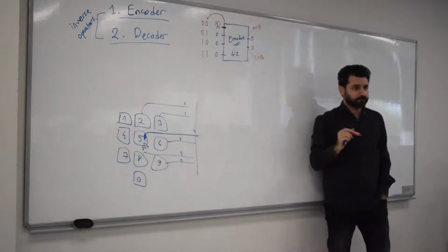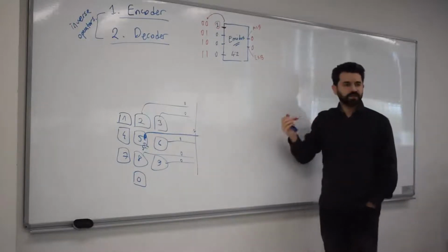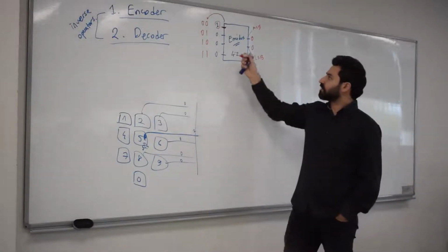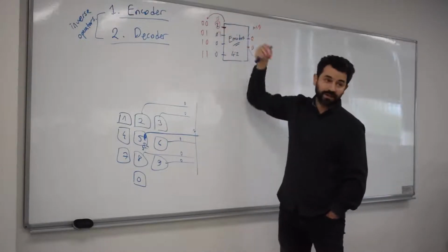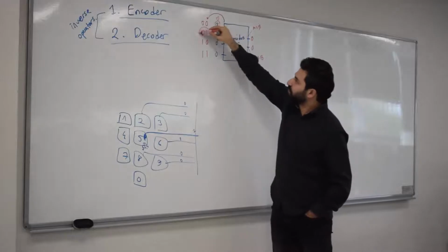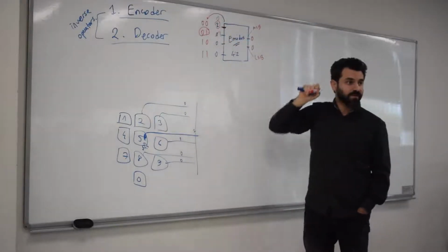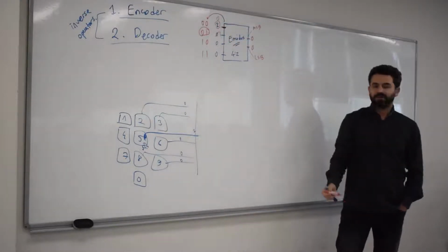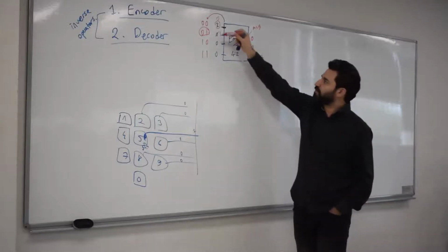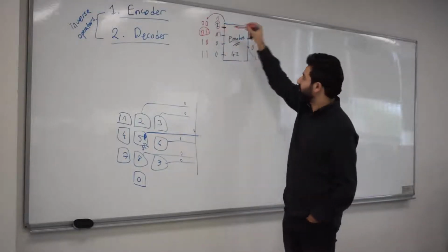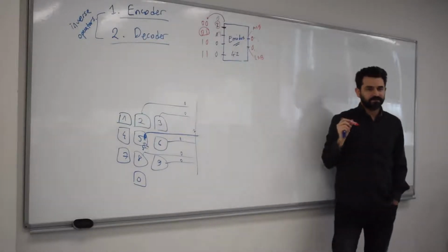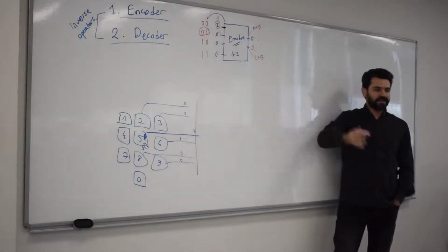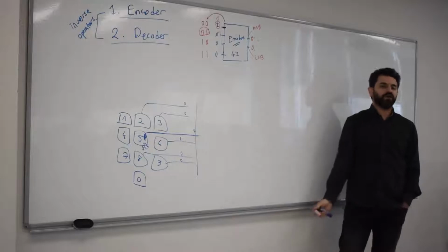All right? It's pretty easy functionality, as you can see. If this was 1 rather than 0, and this needs to be 0 then, this would be pushed out as an output. So the encoder's output in that case would be 0, 1. The most significant bit would be 0, the least significant would be 1. So on and so forth. That's the general description of an encoder.